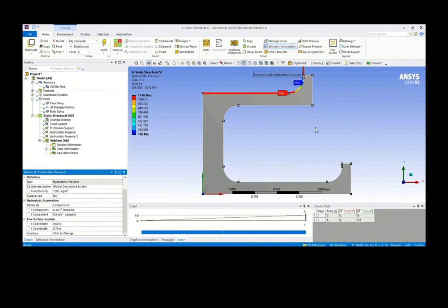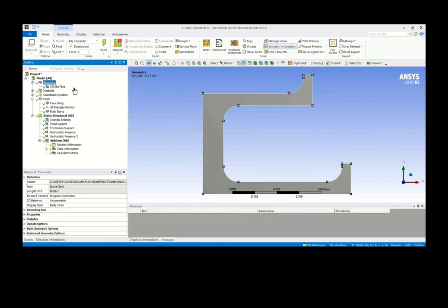So what we can do, at this particular point, let me show you how. Just now we selected this curve, so the top surface of the water is basically this node itself. If you know it, you can key in the XY of that coordinate. If you do not know, you can click on select vertex, then click on this.